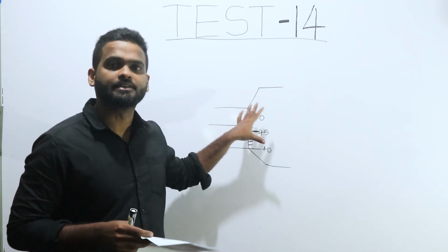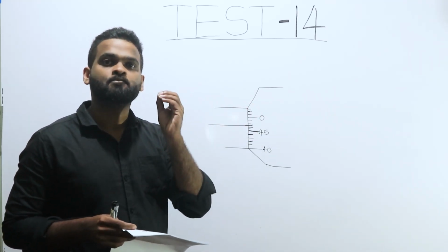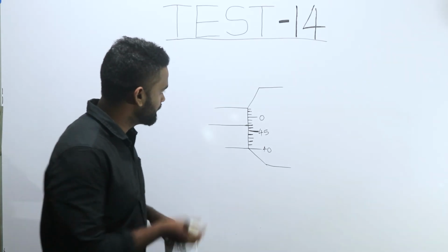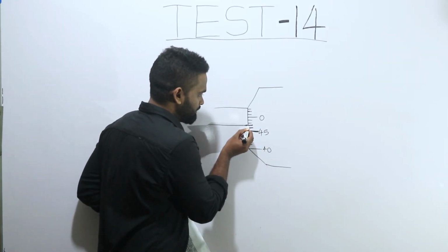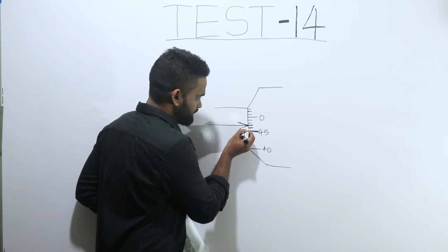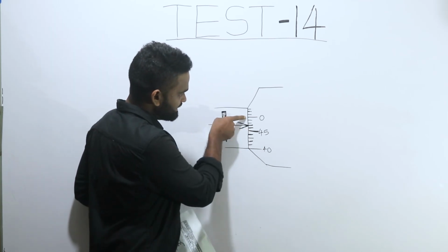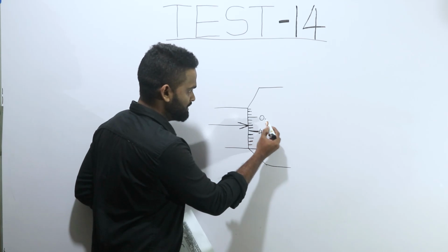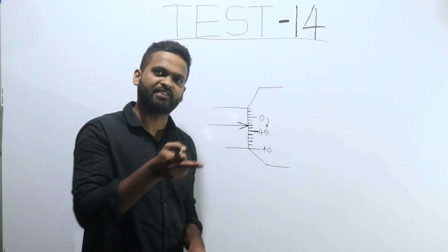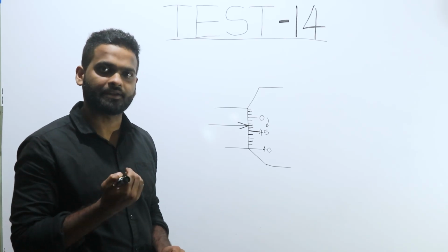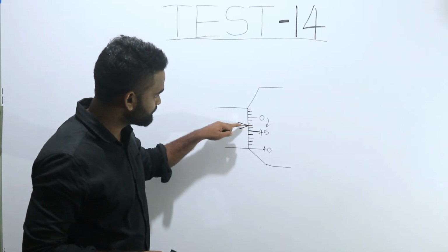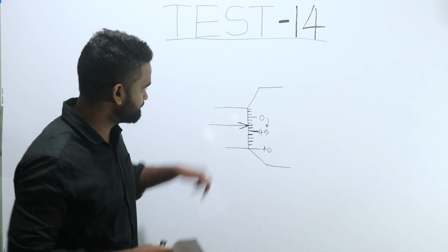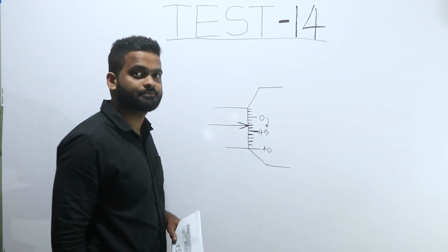When you have to calculate the zero error, the first thing you have to think about is to determine whether the zero error is negative or positive. To figure that out, think about this midline of the linear scale, and it is pointing toward this mark that is below zero. Below zero means you can think that it should be a negative error. Since it is pointing towards the mark which is below zero, you can say that this shows a negative zero error.